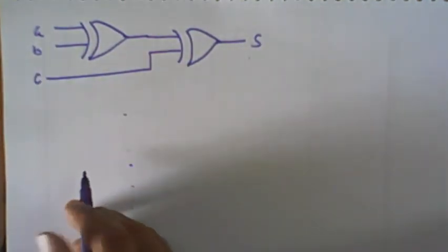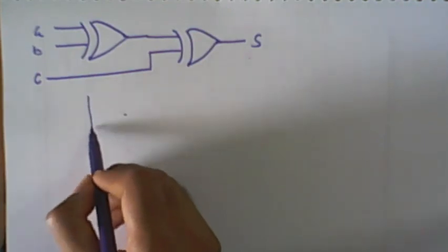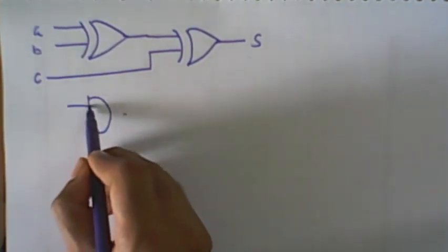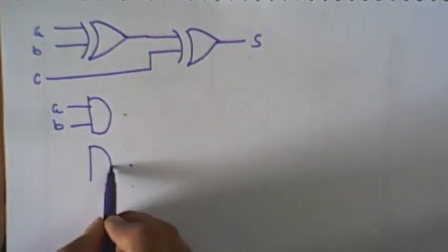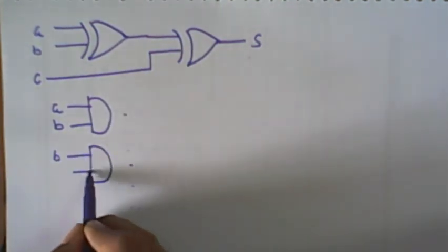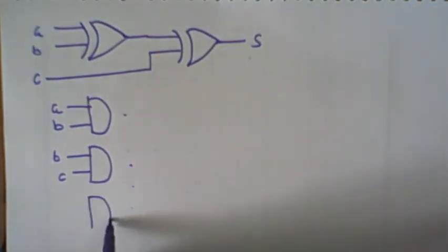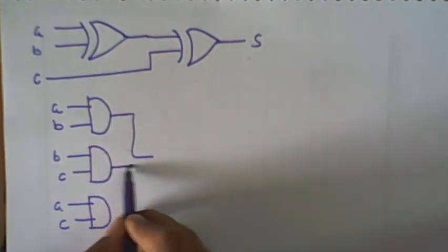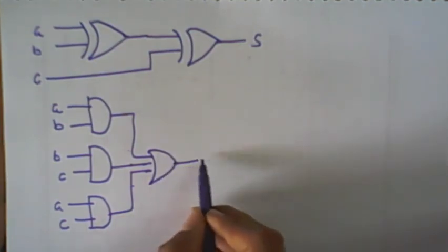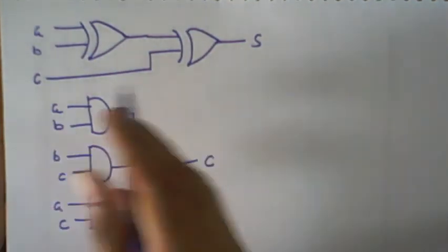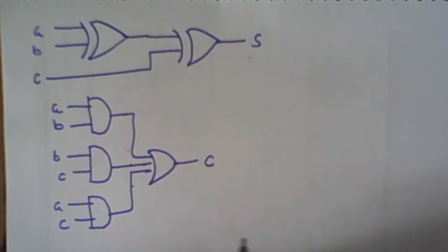It is an XORing of A, B and C. Then for the carry, first is the ANDing of A and B, another product term in the carry is B and C. Third product term in the carry is A and C. And its ORing produces the carry bit. So this is one implementation diagram of a full adder.